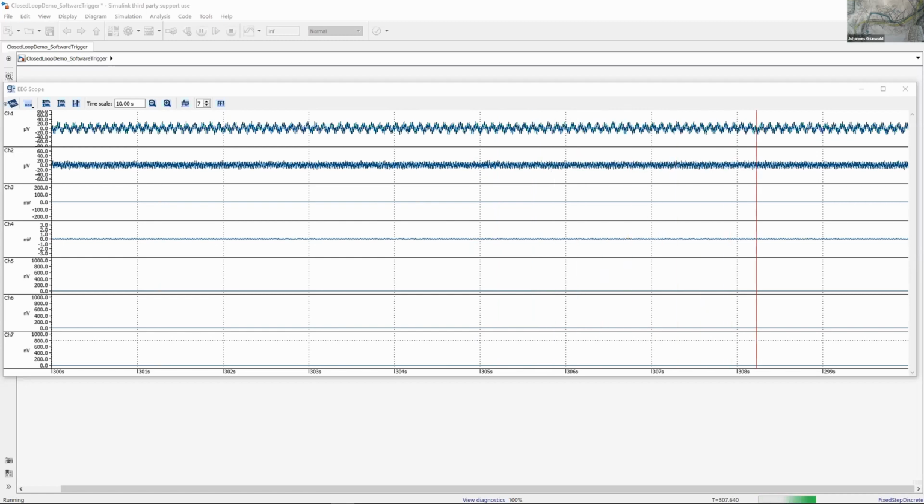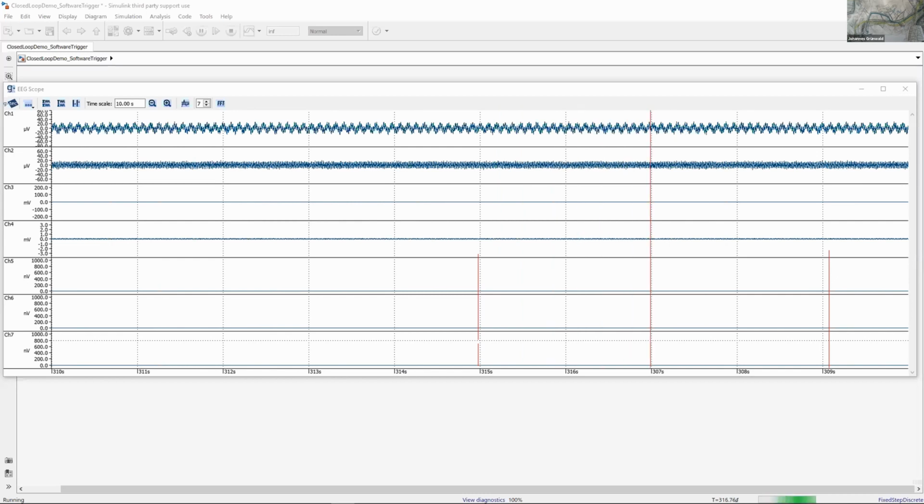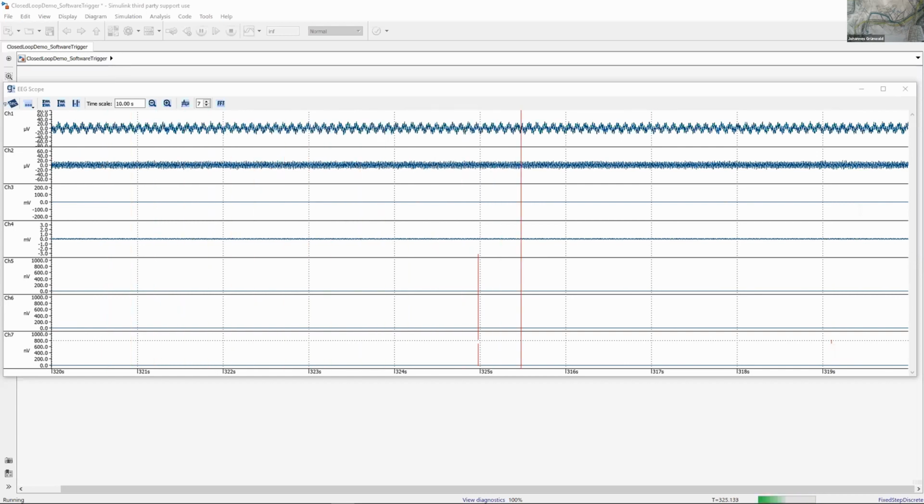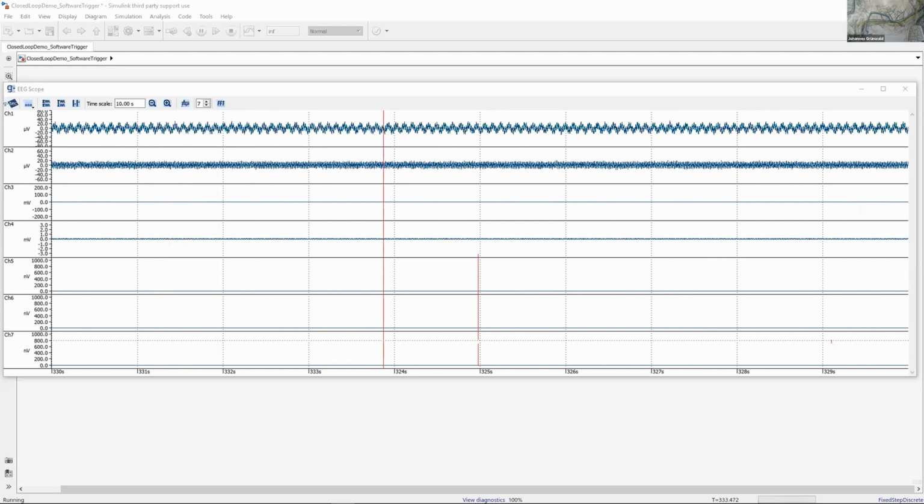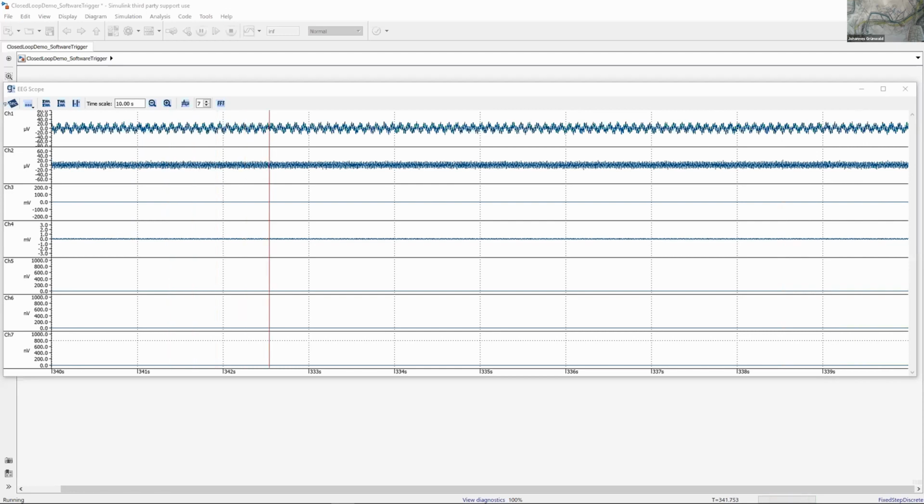Can the g.Estim Pro do high-frequency stimulation? Yes, with the recently released software, we can go up to 500 Hertz for research purposes. How much freedom do you have to modify the stimulus: pulse width, pulse rate, pulse shape, amplitude modulation of high-rate pulse trains? It depends what you mean by modifying the stimulus. If we are below 200 Hertz, then we can adaptively modulate the parameters with the Simulink block. So there is no issue at all. Of course, there is some processing time for the software to communicate it to the stimulator.